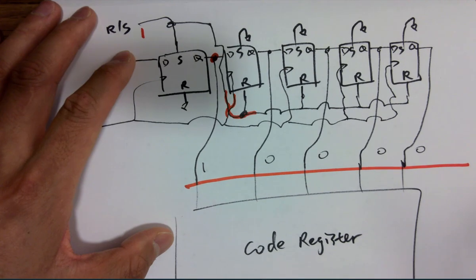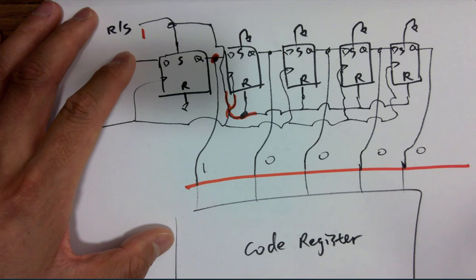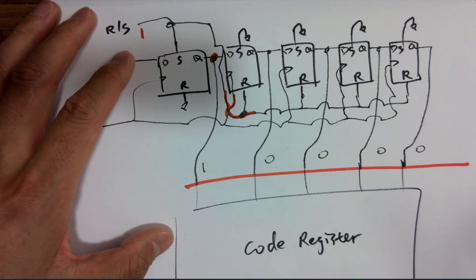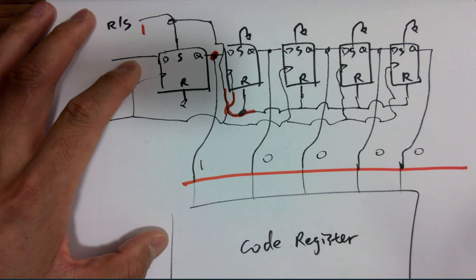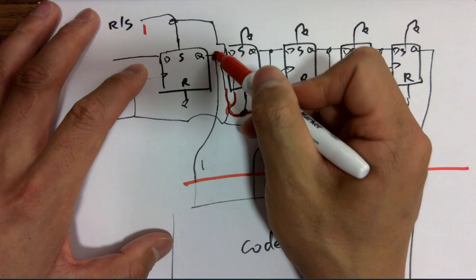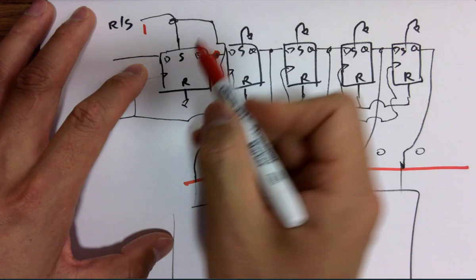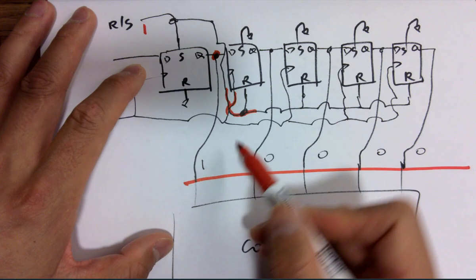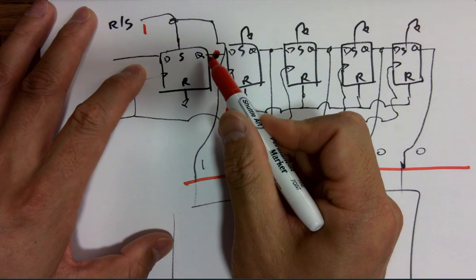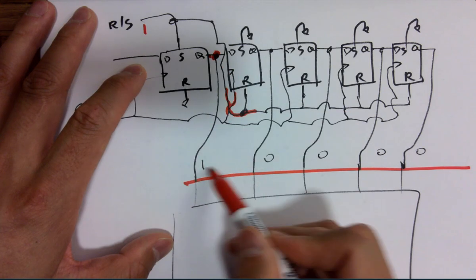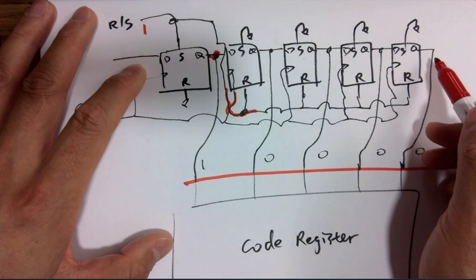Then every clock cycle will push the 1 to the next D flip-flop. Where's the 1 to be pushed from? It would just push whatever is currently set in the first one, from Q, to the next one. Yes, from Q. But the thing is, this is still being set, right? How to do that? Now you have the 1 being latched at the output, because that's a latch, it's going to store it temporarily. And all the zeros are being stored over here temporarily, right?